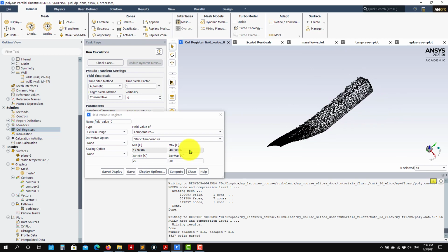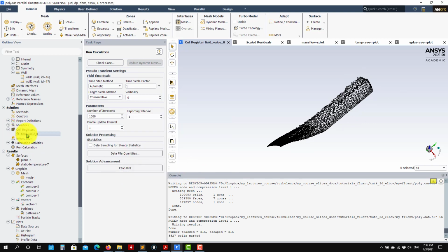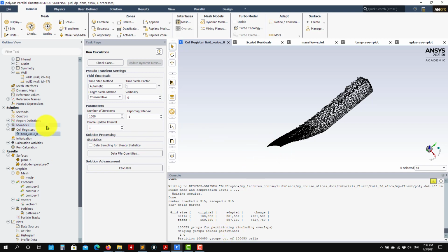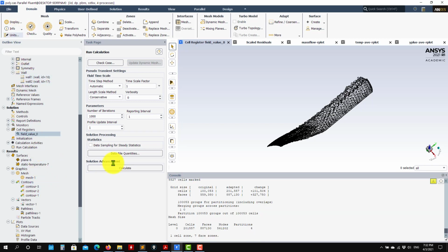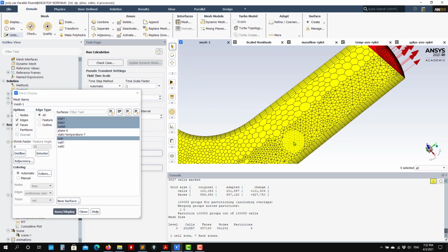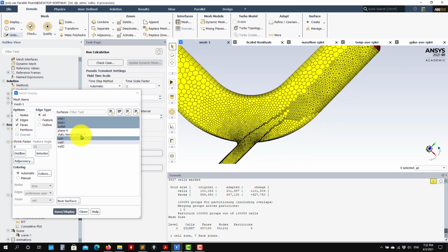So it's up to you to choose. So in this case, for me, I'm happy with this. Okay, you have your register there, and now you can go here, refine, and this is a little bit expensive, it's heavy. Okay, so see that now it refined the cells. Okay, it added almost 100,000 cells more. So you go into cell count, see that now you have 200,000 cells. Previously it was almost 100,000 cells. So as you go here, see that now you see the splitting. Okay, so it's doing the splitting of the cells. Let me put it in this cut plane here.